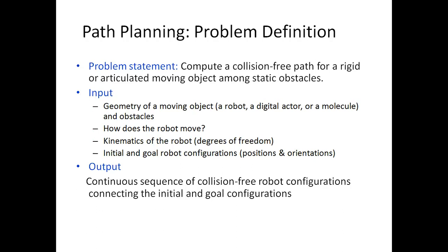What inputs will be required? We'll be requiring the geometry. How does the robot move? What about the kinematics? And what are the initial and goal robot configurations? Similarly, the output will be a continuous sequence of collision-free robot configurations connecting the initial and goal configurations.